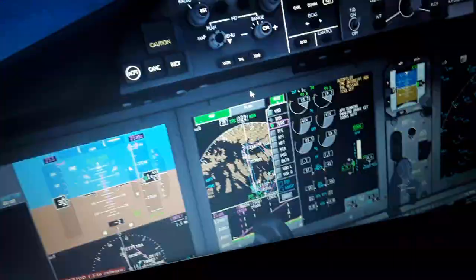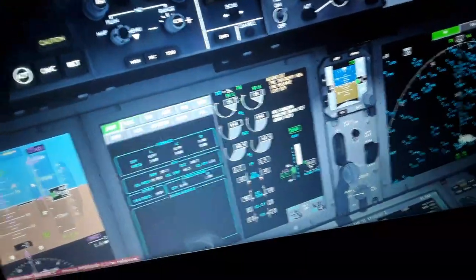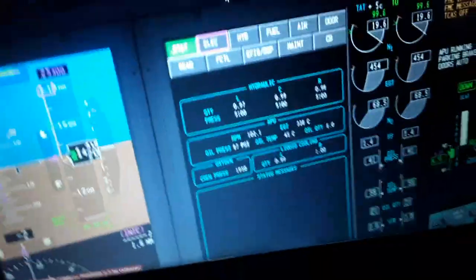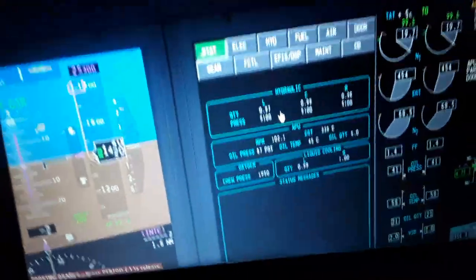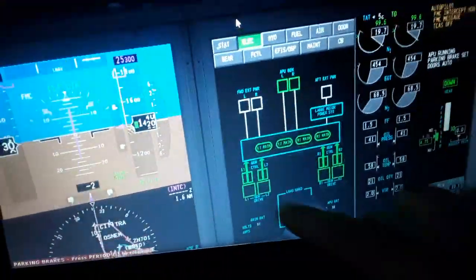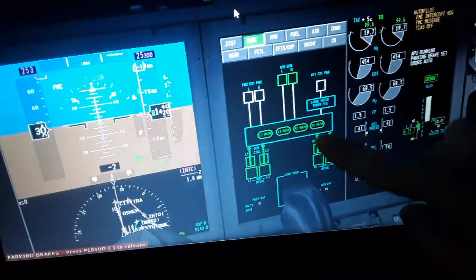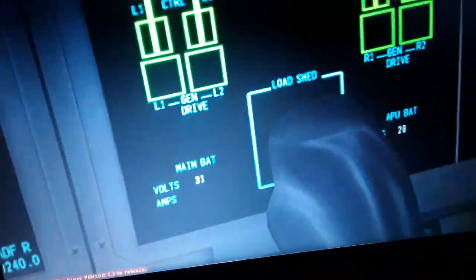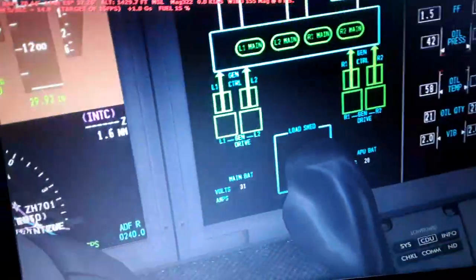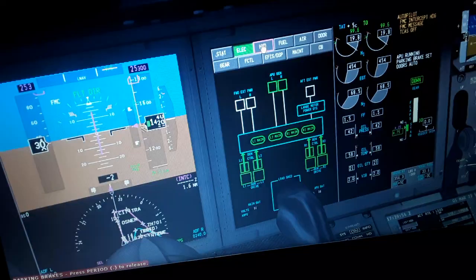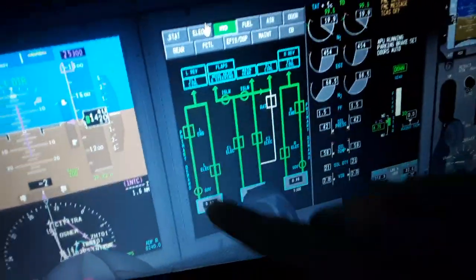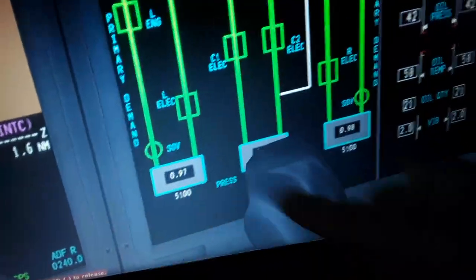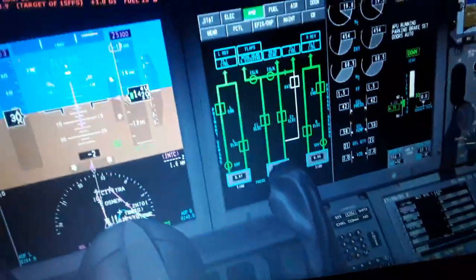So I will show you the last thing here, the digital display of the systems. Just before flight, you will see hydraulics here, APU, oxygen, liquid cooling, the electric, as I told you, left and right engine, IDG, 120, 200 volts, 400 Hz frequency, the battery voltage here, load, battery voltage and average. Hydraulics, where the hydraulic fluid goes, left and right engine driven, electric C1, C2, pressure 5100 psi, shutoff valve.